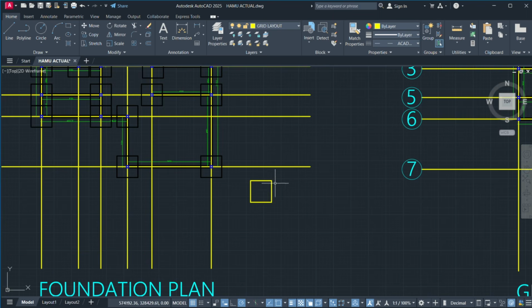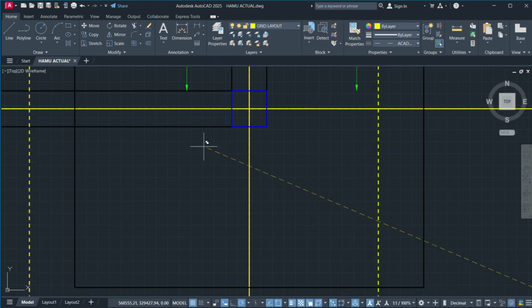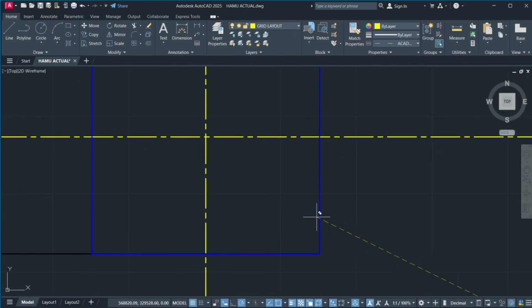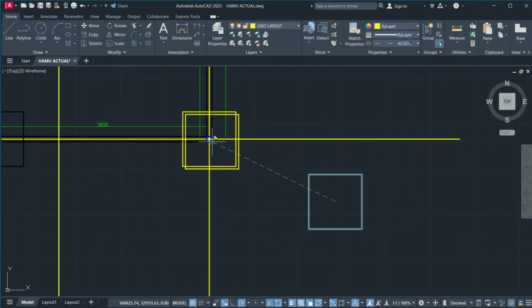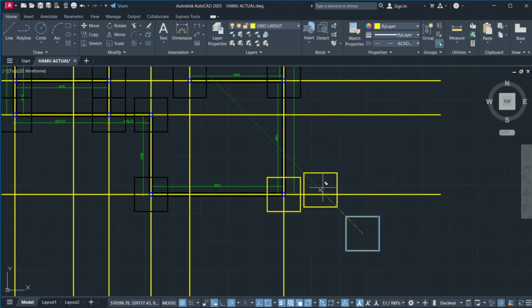1,500, enter. I'll have something like this. Then you can actually decide to copy this. That is when you have already done your plans. I'll grab this center. Now remember that this box that I created, when I touch it on the edges, a geometry center will appear. All I have to do is just place that column on the geometry center and I would have created a part foundation.